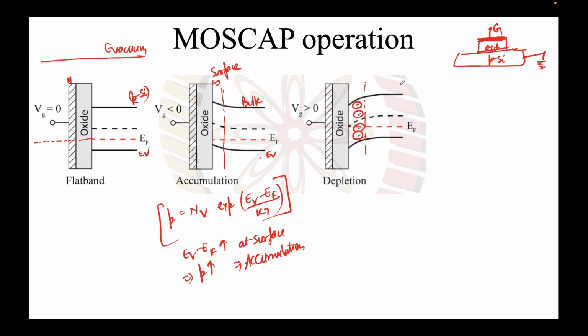The lattice ions, the acceptor ions that you have put, if the holes are repelled away, we'll see that now. What we see is some depletion charge that will appear here, as a negative depletion charge rather. And this process we had talked about in detail.